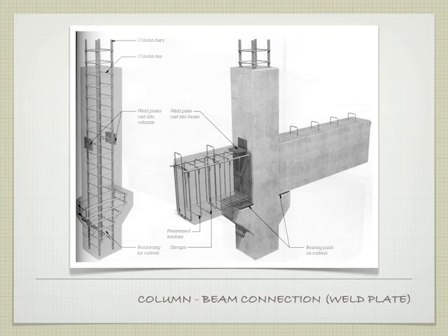It's when we're trying to pull them away. So really the ideal thing is to tie the steel, which is resisting the tension or the tensile forces in one piece, to the steel that's resisting the tensile forces in the other piece, tie those two together, and that's what performs the structural joint for us. So here it is there, welded to the steel cage. Here it is here, welded to the steel cage, and now the two get welded together.